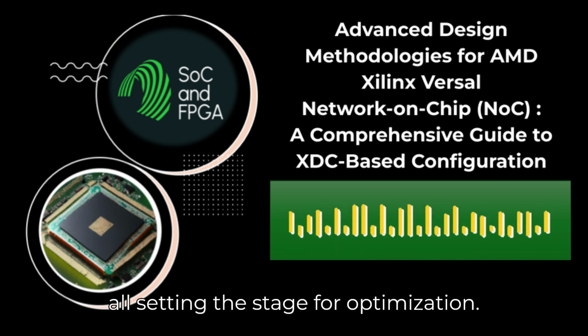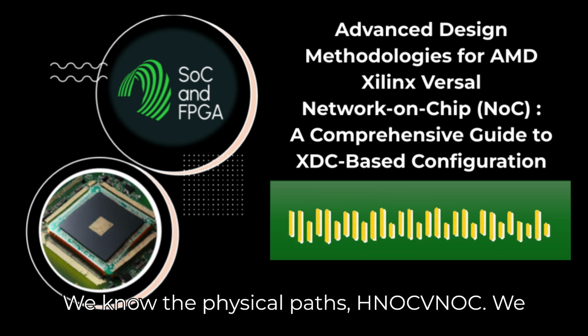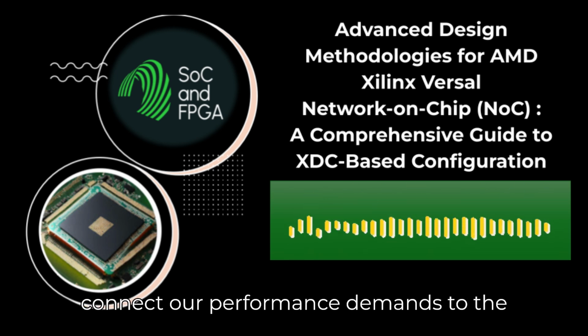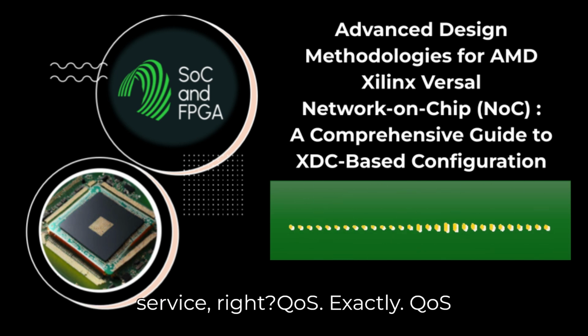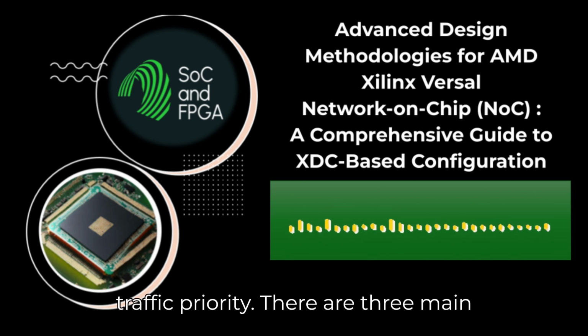All right, this is all setting the stage for optimization. We know the physical paths, HNOC, VNOC. We know we need XDCs for control. Now let's connect our performance demands to the physical chip. Starts with quality of service, right? QoS. Exactly. QoS is how you tell the NoC compiler about traffic priority.